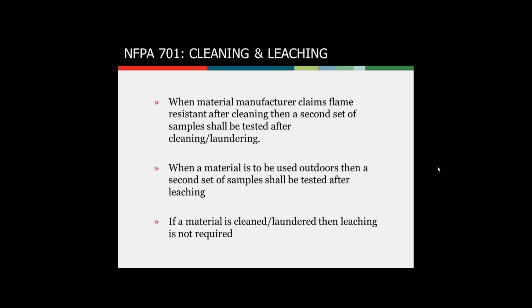Specimens are cut from material after laundering and conditioned as per the test method. Leaching is performed if the materials are to be used outside. 72 hours of leaching in at least 15.1 liters of 20 C water is required, with the water changed from the leaching vessel every 24 hours. Specimens are then cut from the material after leaching and conditioned as per the test method.